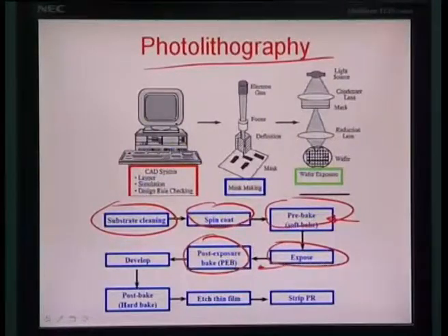So you pre-bake, also called soft bake, and then you expose the pre-baked resist to light using a masking step. The photo exposure and the post exposure bake are carried out at this stage so that it catalyzes the way the resist can set in on a surface. Otherwise, if you had just pre-baked and exposed, it would take some while for the photoresist to diffusively get to different parts of the resist where it would create cross bonding action.